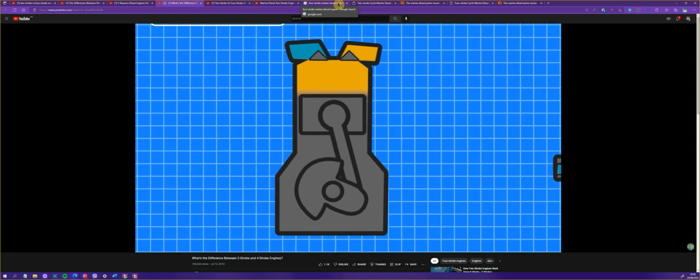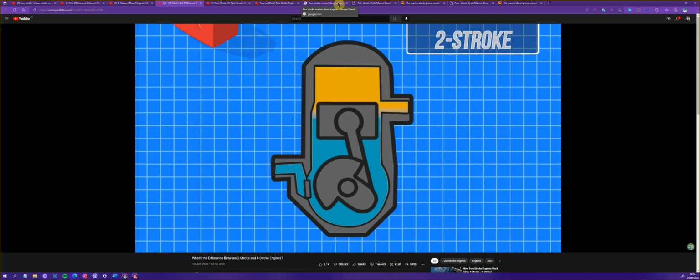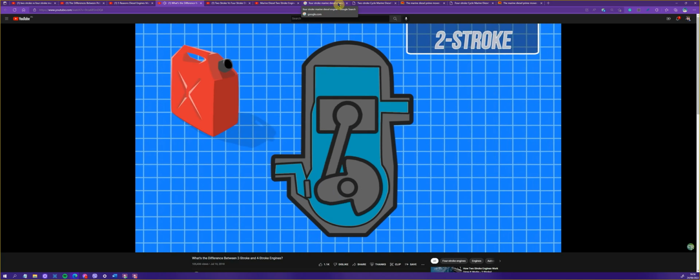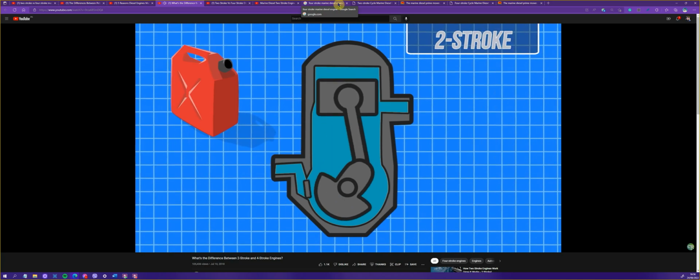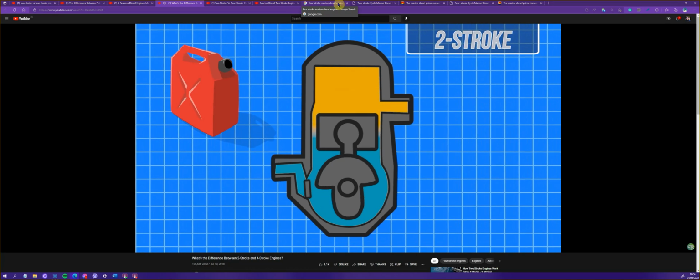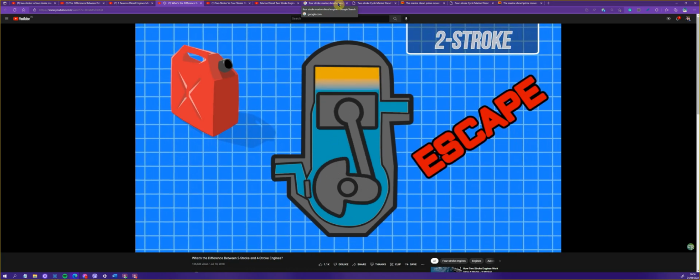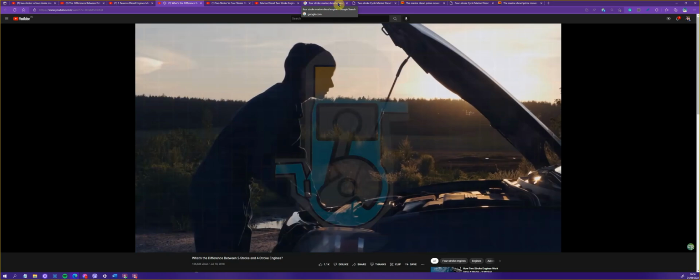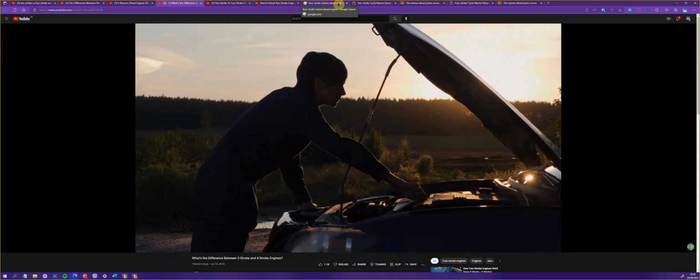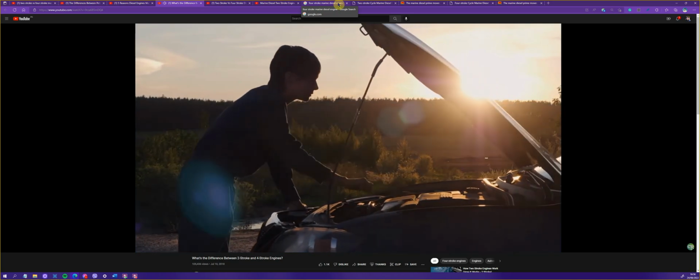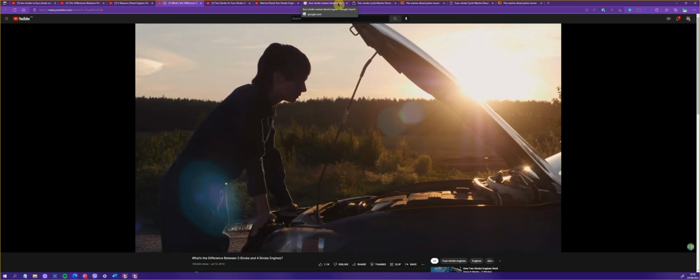In a two-stroke engine, since the fuel is drawn in during a combined intake and compression stroke, the mechanics needed for this also means that some fuel can escape while being drawn into the cylinder, thus decreasing efficiency. Modern two-strokes use fuel injection, which increases their efficiency to levels close to four-strokes, but generally, a four-stroke can be much more efficient.